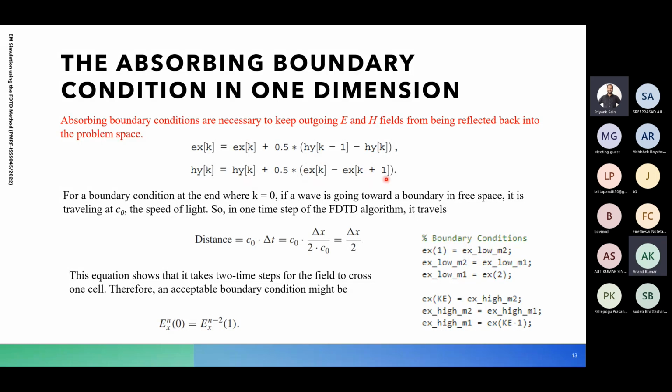Okay, but I thought in space also there might be some causality. So before excitation, all the fields remain zero, and when we provide an excitation, in our codes we are giving the excitation on the electric field, and this electric field gets updated, and using these values we update the magnetic field. And before the excitation, the fields are zero.